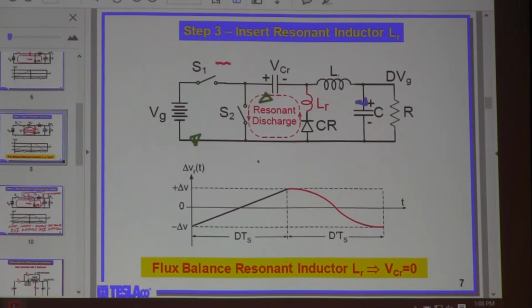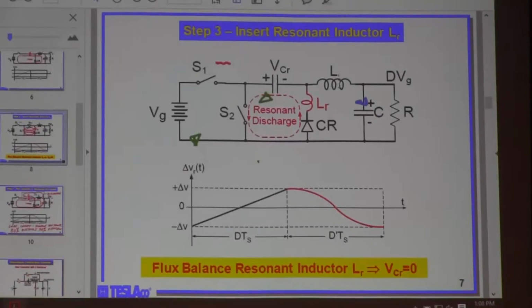And you know what that tells you? Total charge and discharge have to be the same. If I put all the charge to the output and now all the discharge also to the output, what does it say? I have twice as much current to the output, twice as much power, right? And what happens? My stresses in this circuit and the one connected to the output, voltage stresses are the same. Current stresses are the same, except I deliver twice the current and twice more power.